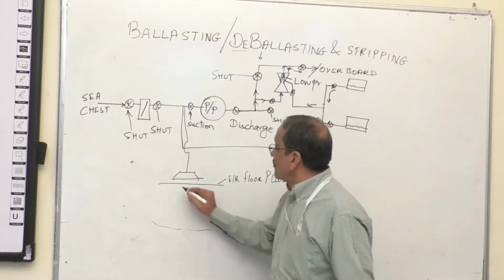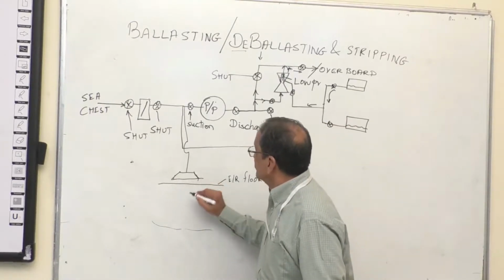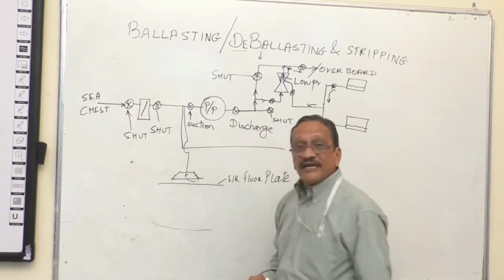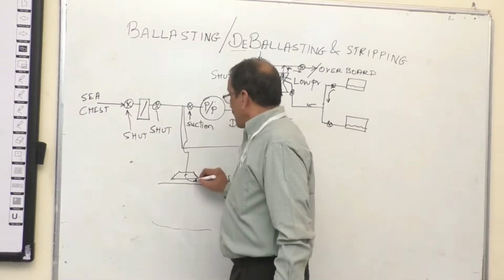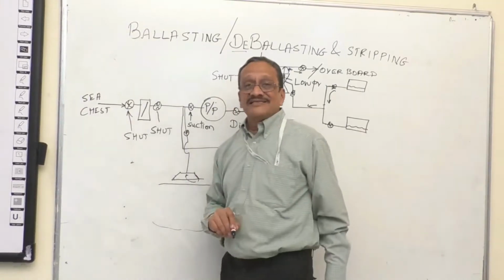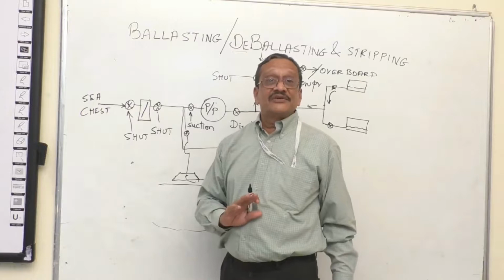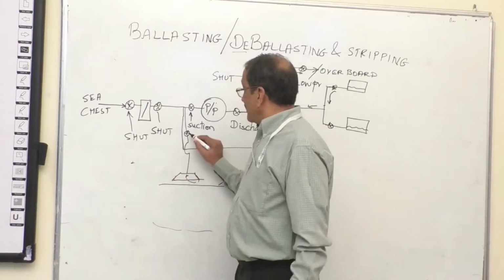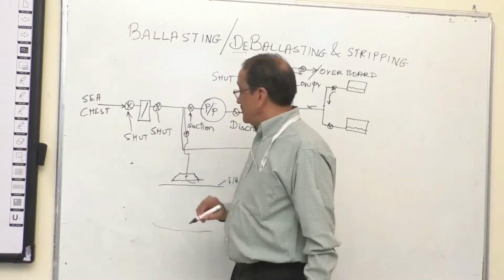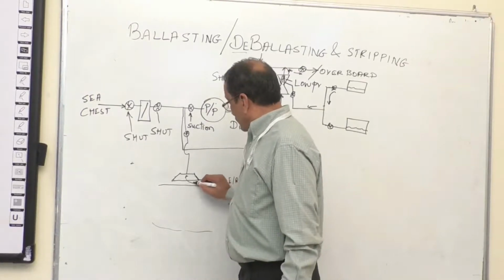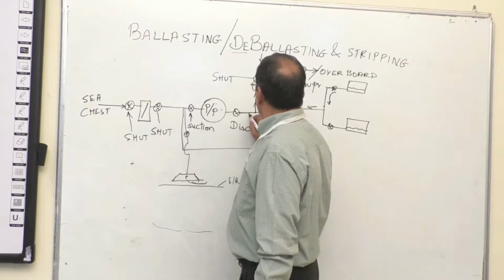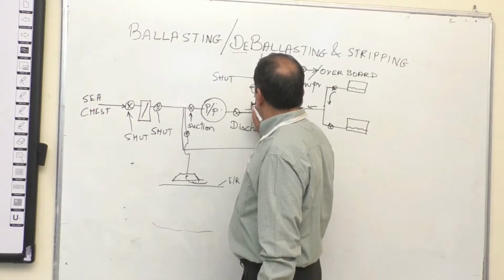That's an engine room flow plate, and this is the plate. Supposing there is any flooding taking place over here, I have this water passing through this point over here. I also have an emergency bilge suction valve, which is connected to the suction side of the pump, which is going to take the water from here, pass it to the pump, and from the pump I have the line which is going in over here.